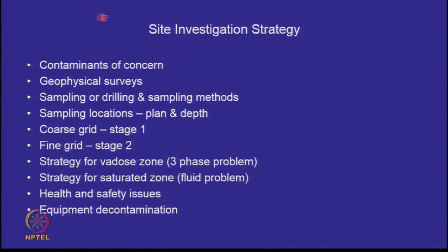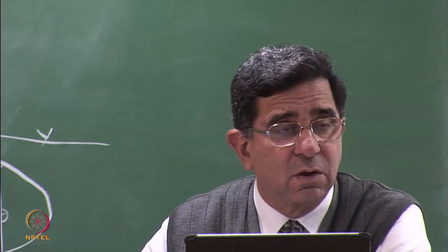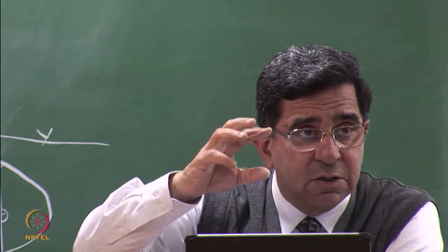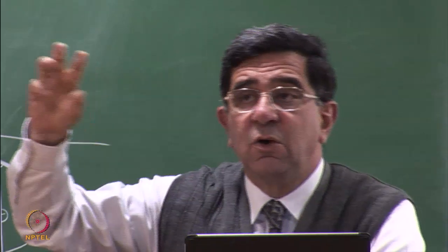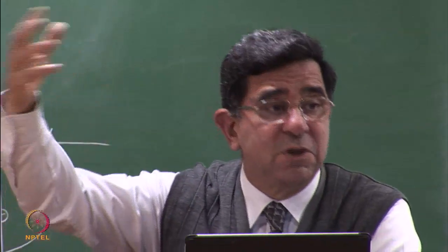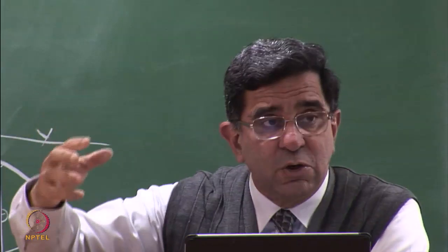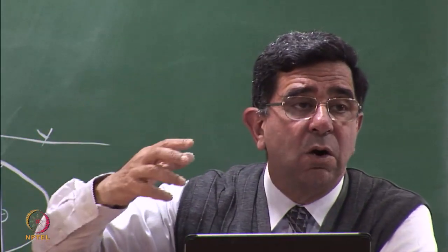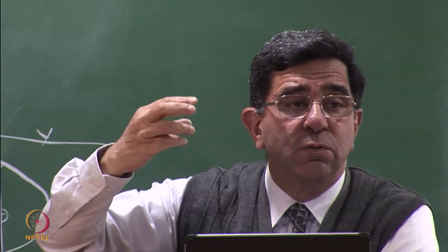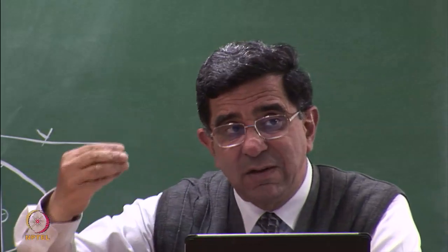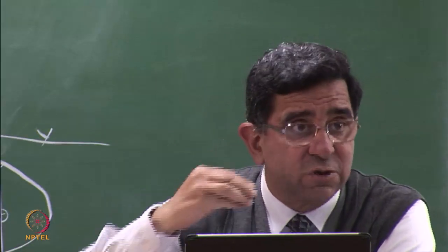So normally it takes this shape from the leachate of the old dump. Please find out the contaminants of concern. Analyze the leachate, and tell us which are the contaminants which are above the prescribed limits or the background. Compare the constituents of the leachate with the constituents of the groundwater which is on the upstream side. Those which will cause the groundwater to have elevated levels, those constituents are of interest to you.